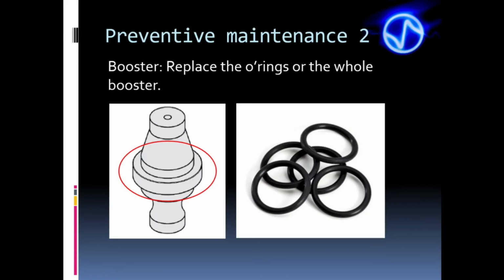Because if the problem is tuning, it's necessary to change the booster dimensions to correct the frequency deviation. Changing the dimensions has the adverse effect of changing the gain of the stack and may even affect the nodal position, decreasing its performance even though it's tuned. If the booster is out of tune, it's best to replace it. Furthermore, if the booster is cracked, it must be replaced anyway. Summing up, if the problem is not the rings, replace the booster.